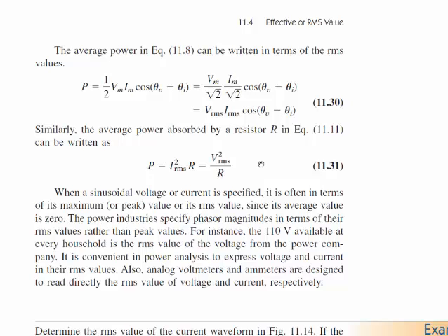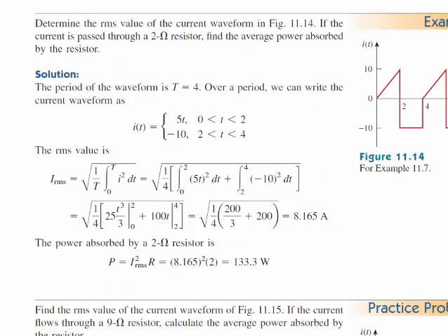So doing the RMS will absorb these square root of 2 things that occur. And the square root of 2's are also where that factor of 8 came into play in the denominator in the maximum power transfer equation. So you can apply RMS, the definition of an RMS or an effective value, for any kind of shapes of functions.